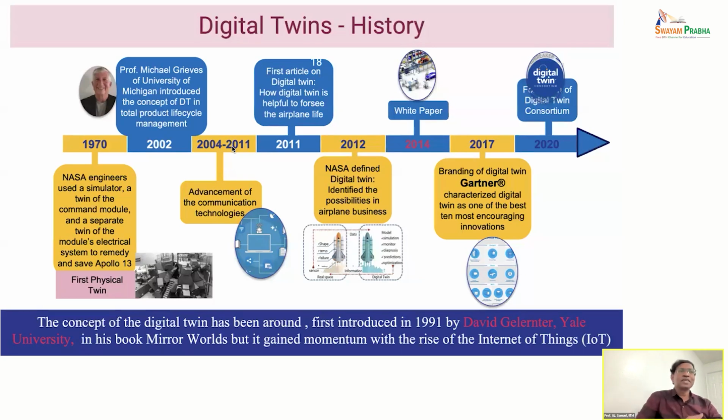improved. See now, for example, if I'm turning a part, think that due to tool wear the dimension is increasing. In turning, if the tool becomes smaller, the dimension becomes bigger. So if I had an inspection step there, I can get the data and then send it back to the machine.